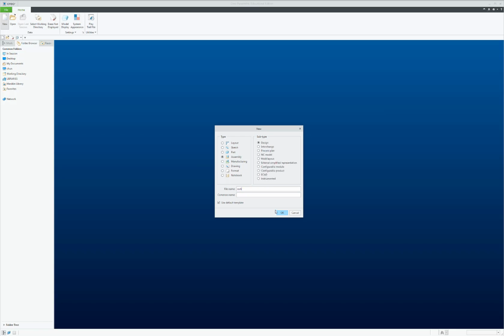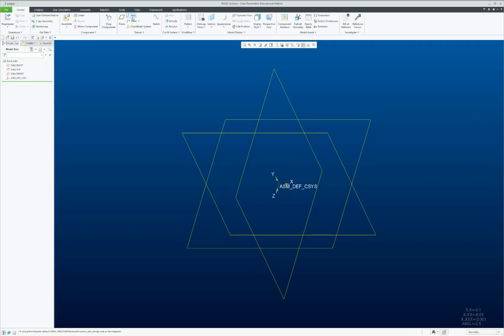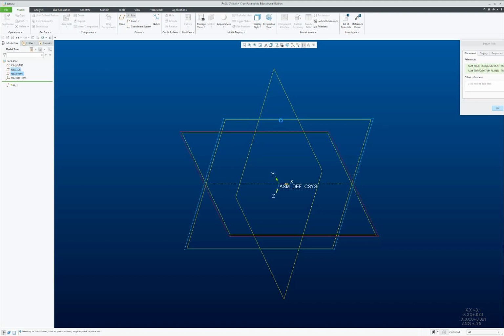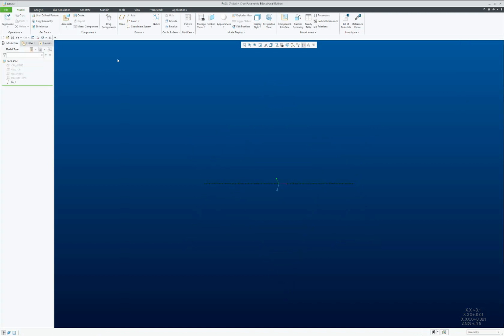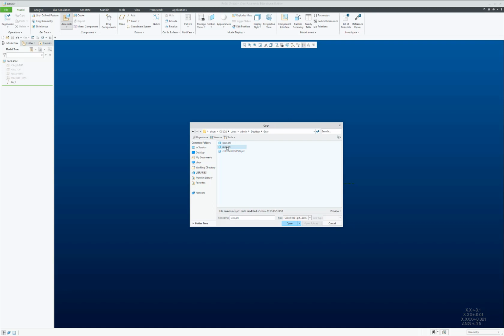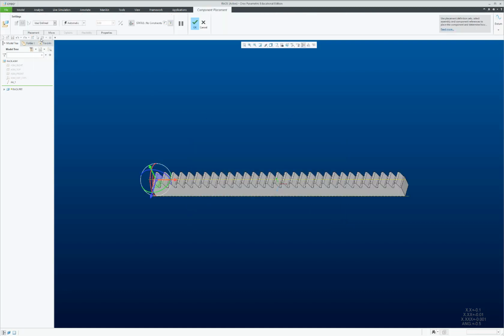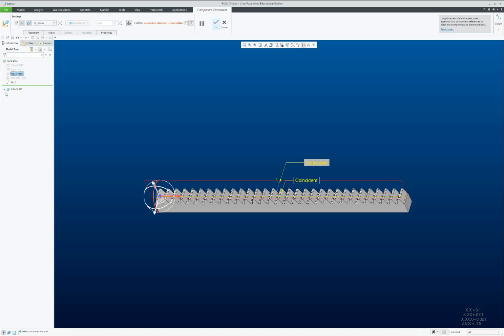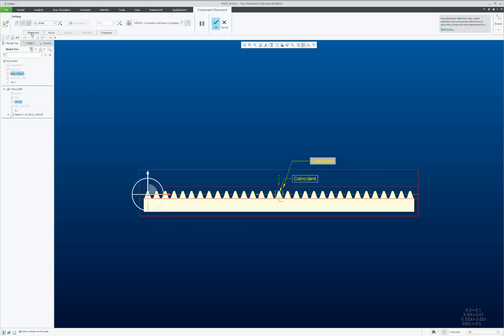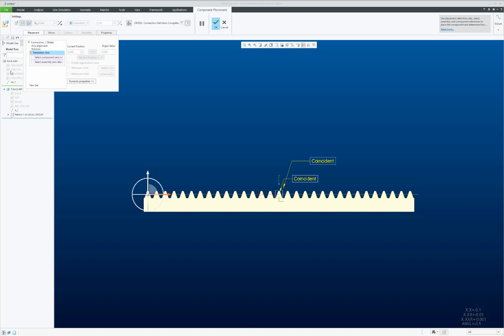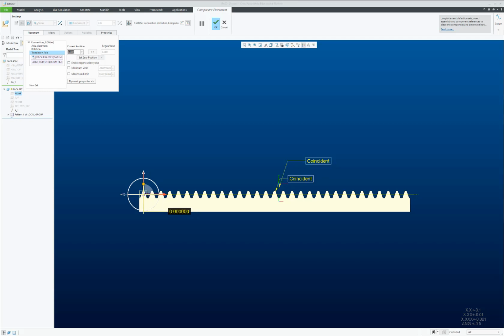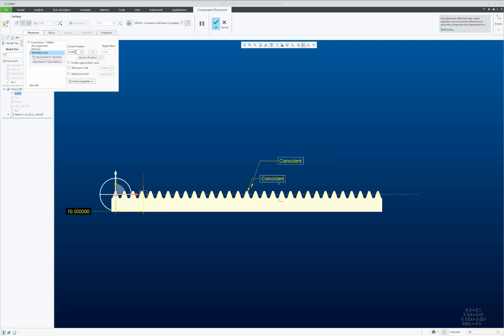and is in assembly. Create the horizontal axis and hide the planes. Assemble the rack with a slider that goes axis, front plane with front plane. And taking a look from the front, we would also like to set the 0 position between the right planes of both components. Place that in 0. Let's give it a positive number to observe the direction, and that is good.